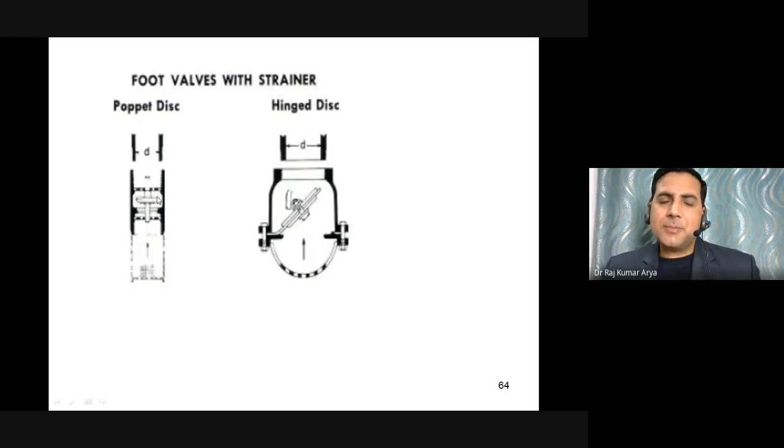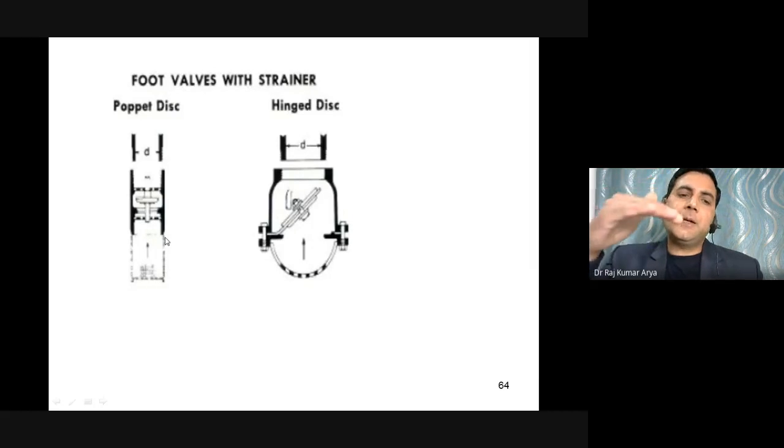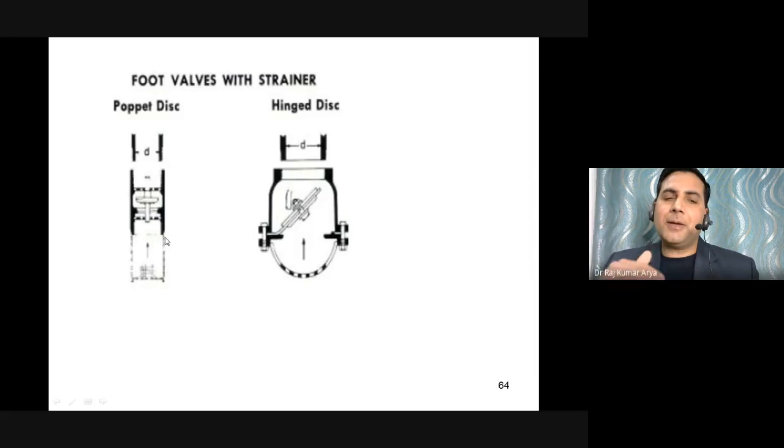So this disc will make sure that the bottom of the pipeline is always filled by the liquid only, so that whenever you turn on the pump, you are just creating a suction just to lift the disc, not to lift the water from 100 feet down. Okay.